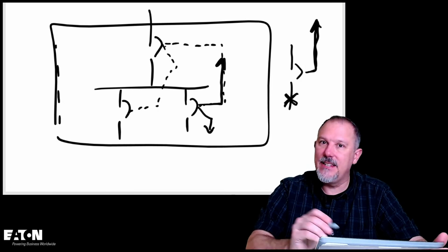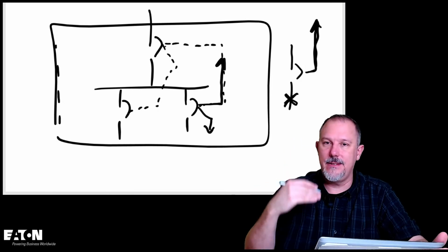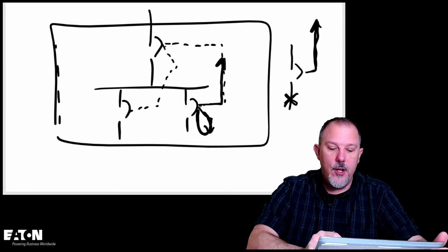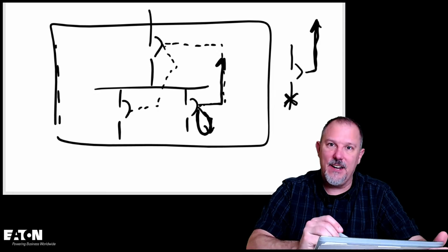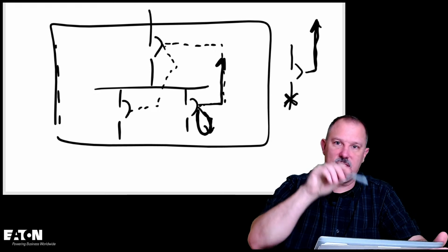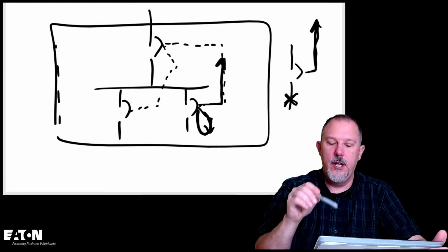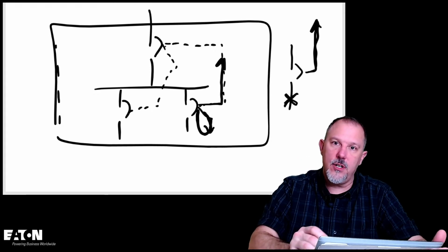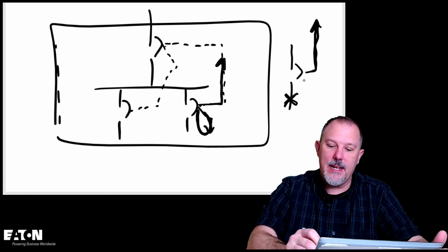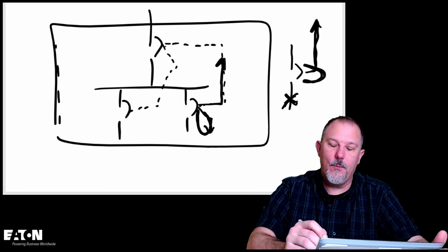If it's the last device in your series system, what we do is we jumper this back on itself. So when it sees a fault, it sees its own signal. So if I take this breaker out of the cell and I put it on a test bench, I'm going to want to jumper it to itself.